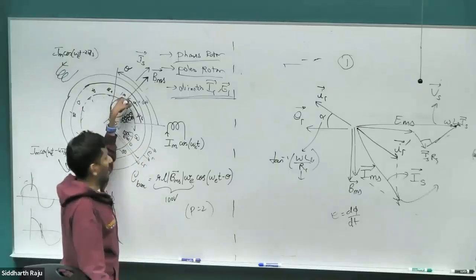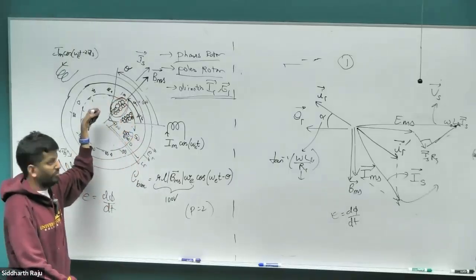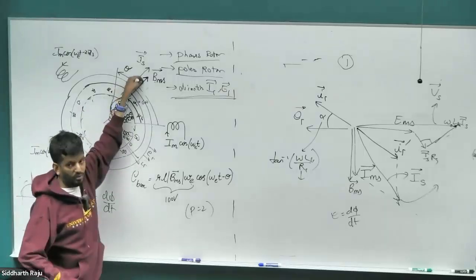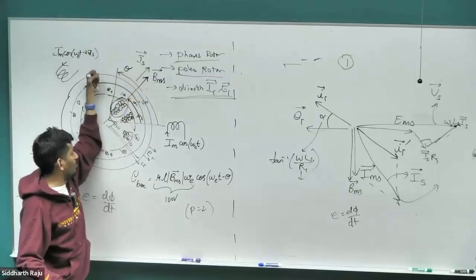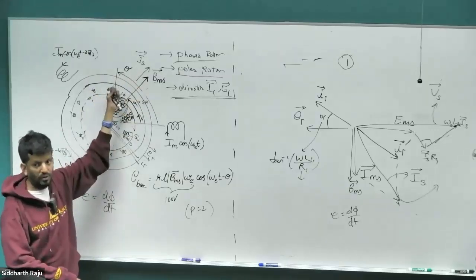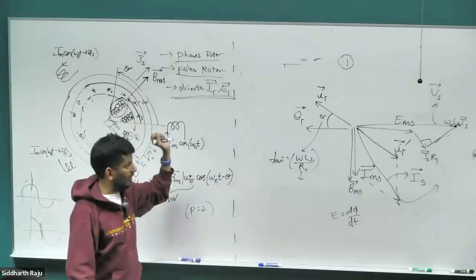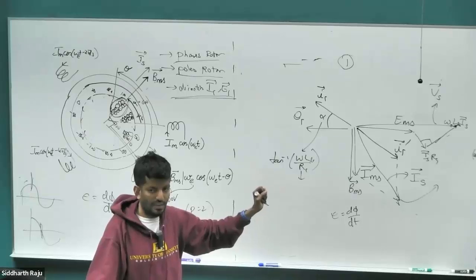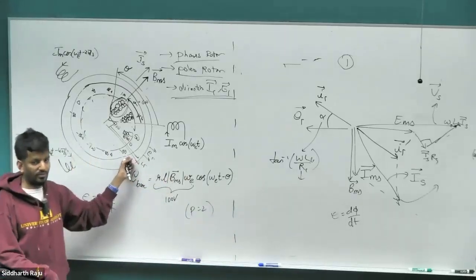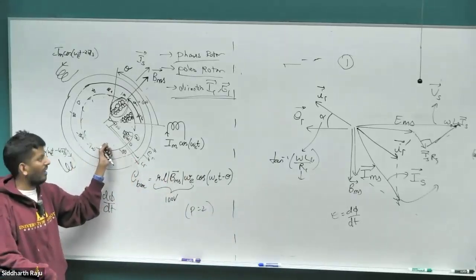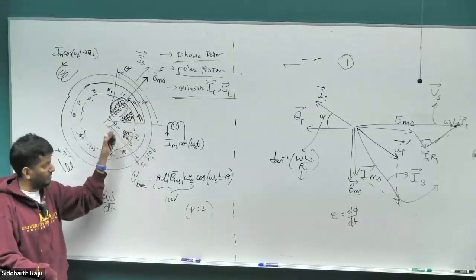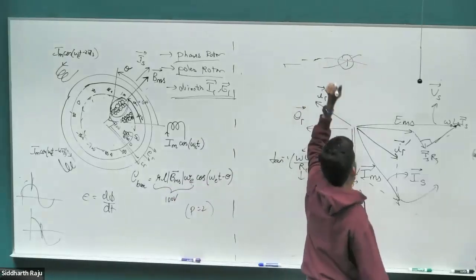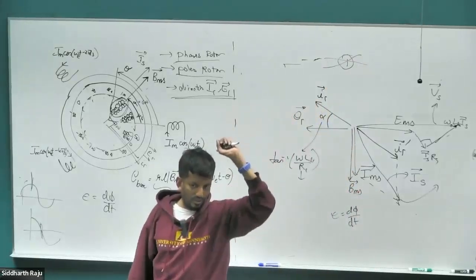But in our case, the rotor magnetic field is rotating. The rotor EMF space vector, which was along this direction when the B space vector was along here, as time went on, as B rotated, the rotor EMF and rotor current would have rotated along with it. So if I'm trying to model the rotor as an equivalent circuit, and I model it as a single phase system, I cannot create rotating fields on the rotor. But clearly the fields on the rotor are rotating by virtue of coming from the stator. So it cannot be modeled as a one phase network. Is that clear, Jonah?